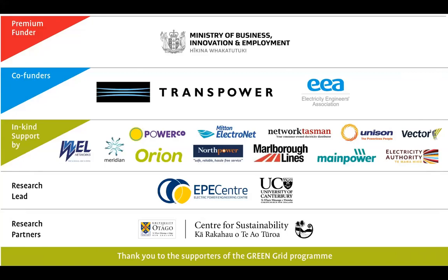When modelling the electric vehicles, there's no dependence in my model on time of year. Perhaps there is a dependence. Perhaps people drive more in the winter than in the summer, but I don't have that information, so my model has to assume at this stage that people's driving doesn't depend on the time of year. On the other hand, the non-EV load in the smart meter data set varies considerably throughout the year. The particular week that I picked was the week which had the peak load in the data set I use. So it will give you an indication of the time of year that transformer loading, network currents and network voltages are likely to be at their most extreme.